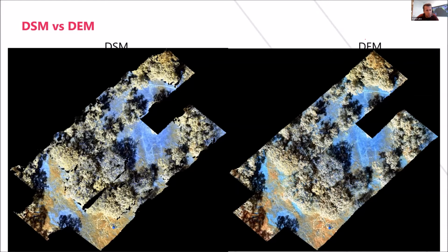So you can see when you use the elevation model, you have overlap everywhere, but you have the co-registration problems between the flight lines. While here, when they use the surface model, they have the co-registration they need between those 2 flight lines, but here they have a gap because they have planned it that the distance to the ground is higher. So then you get better overlap, while now the distance to the ground is lower and actually the flight lines are not overlapping at all. So this is important, at least if you're flying UAV systems, to plan it.